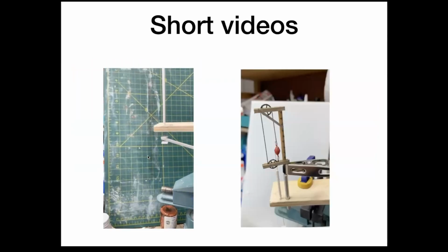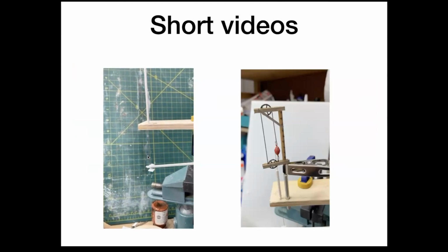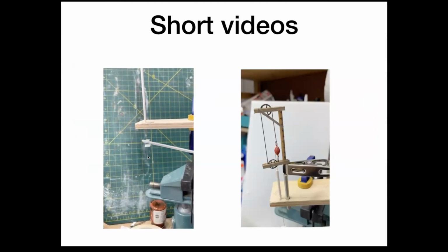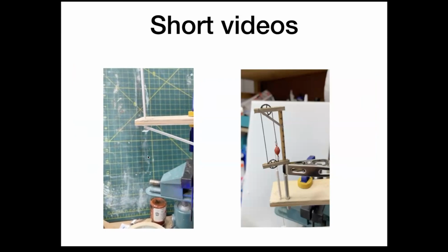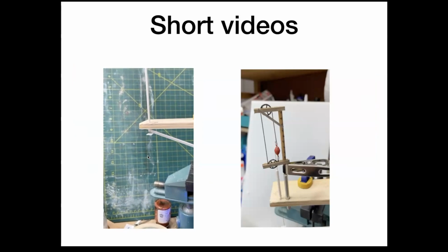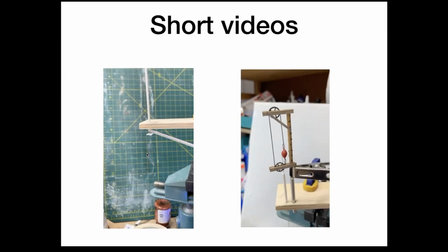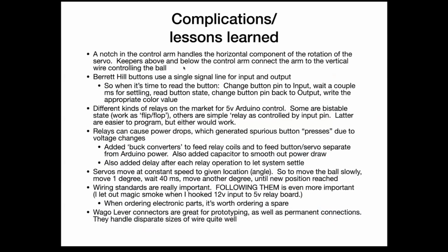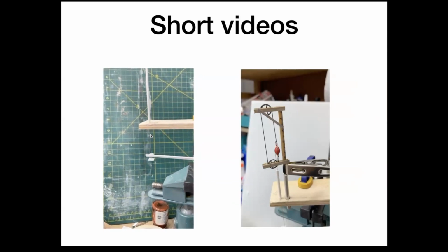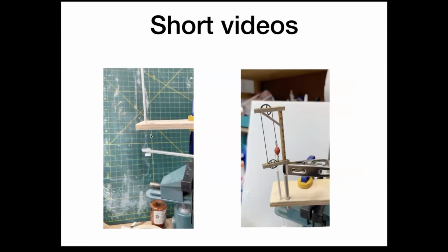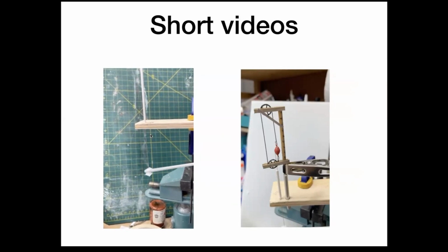I just want to show the servo, which you can't see, is slightly off to the right-hand side. The way I handled the motion here, when that arm pivots, there's a little bit of horizontal motion. And there's just a slot in the arm so that the vertical rod moves up and down, but if you look carefully, you can see that in that slot it's kind of moving.